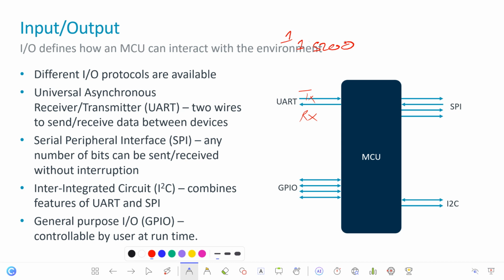The UART transmitter converts the parallel data from the MCU into serial data before transmission. A UART receiver performs serial to parallel data conversion at the receiving device, and the data flows from the TX pin of the transmitting UART to the RX pin of the receiving UART. Of course, this is the basic form of communication.